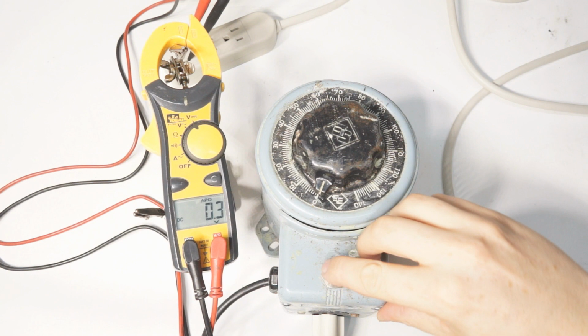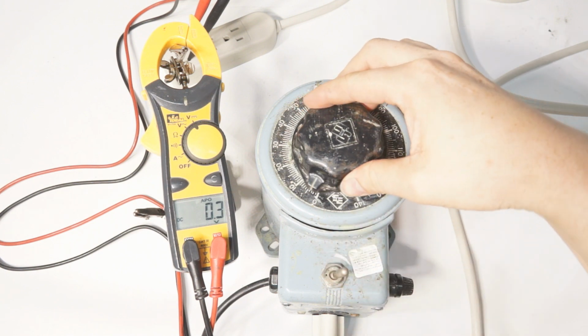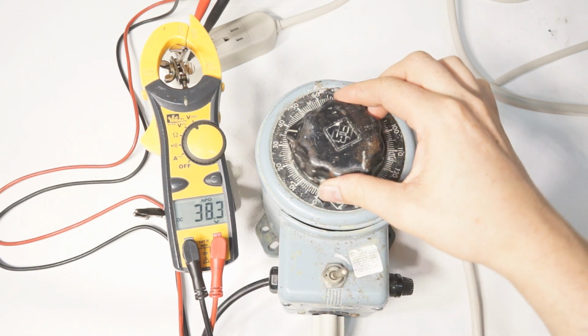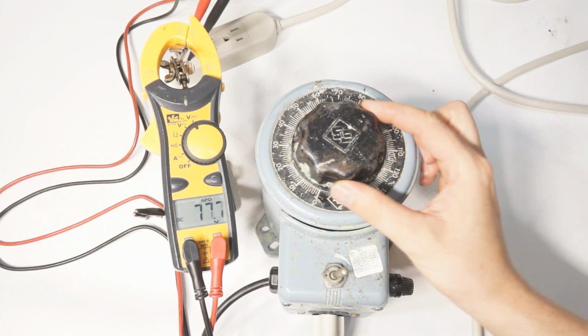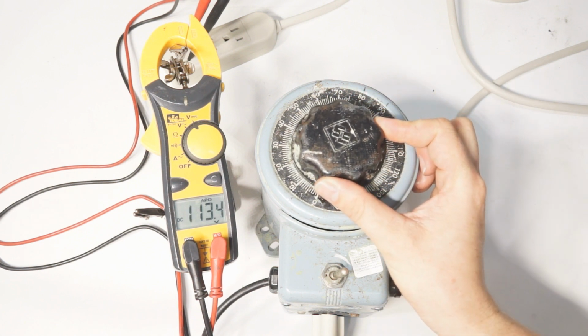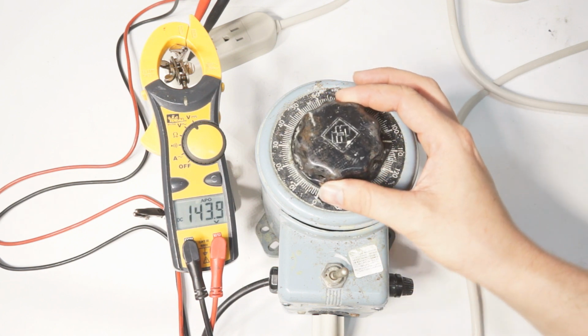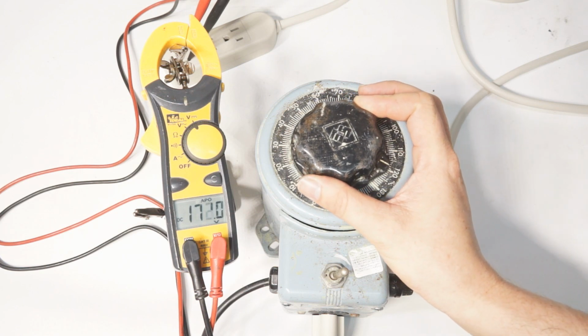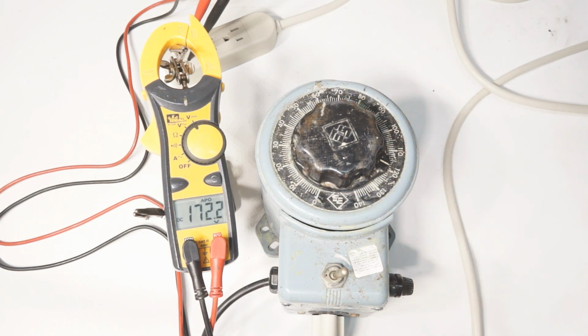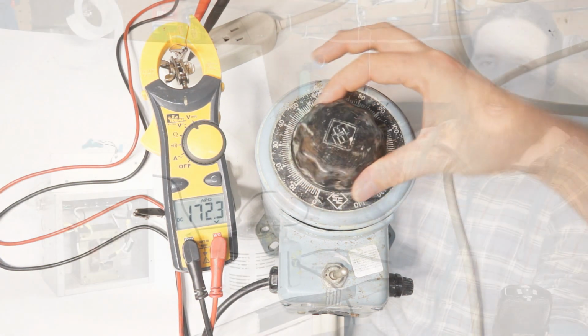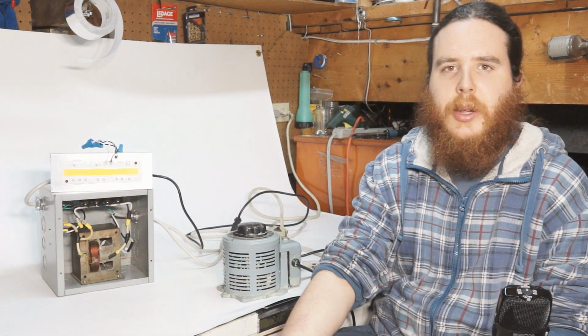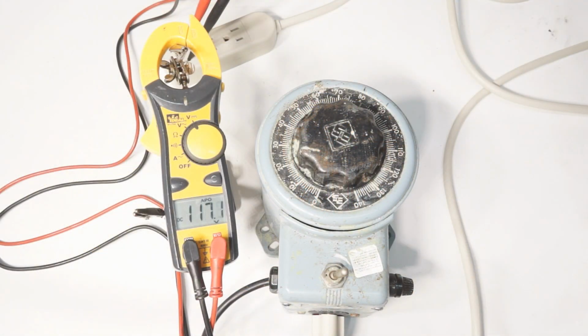When using my filtering DC supply, I only have to give it 80 volts RMS in order to get the 110 volts DC that these LEDs need to run. Had I plugged my filtering DC supply directly into the line, they'd be getting 170 volts, which significantly shortens the lifespan of the LED. The other problem with my power supply is that the capacitors hold a significant amount of